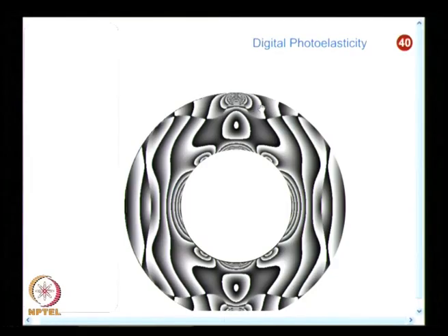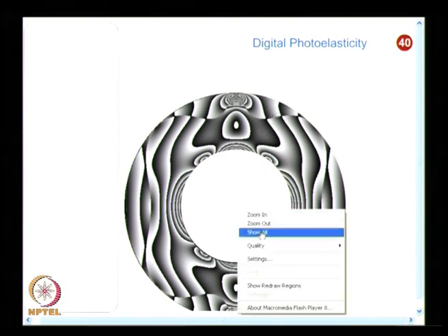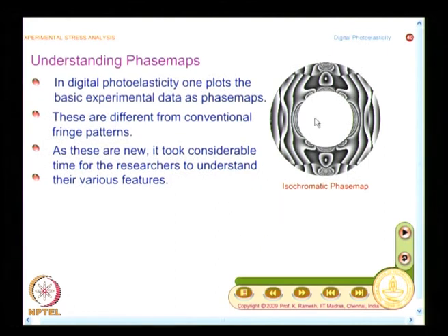In fact, our group has identified that if you find the principal stress direction of one of the principal stresses consistently, you do not have the problem of these kinds of distinct zones, and this is also labeled as ambiguity. This was resolved by determining the isoclinic value for a particular principal stress.